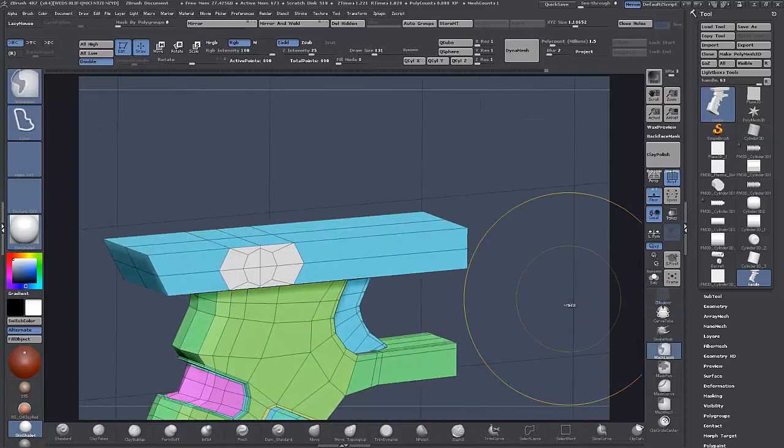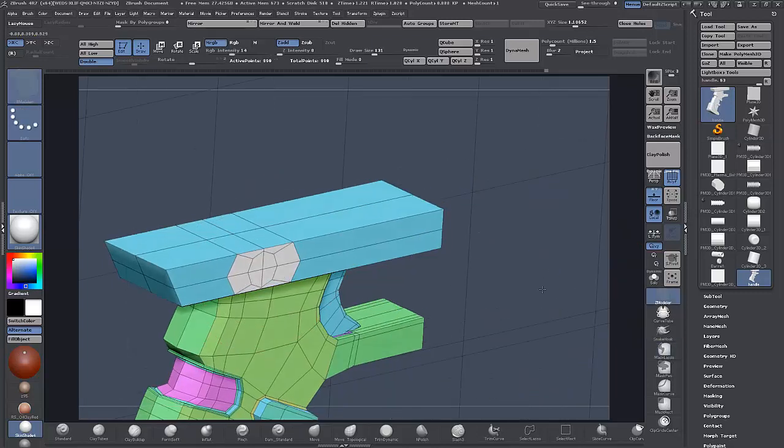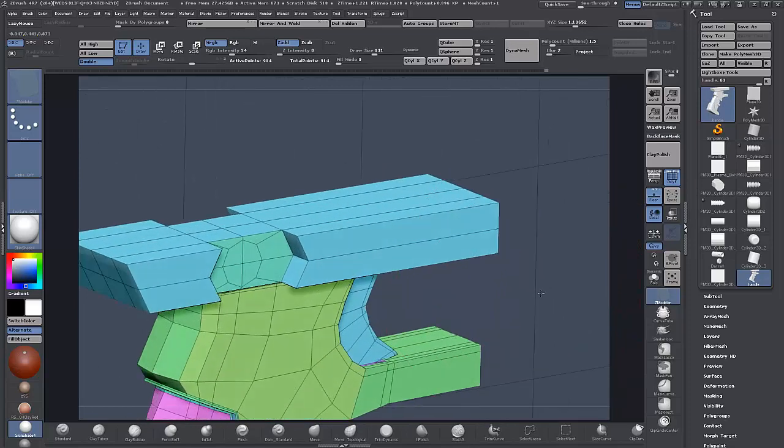Now the only problem here is, I might just insert the loop. Got a circle out there, and then we can tag these. Maybe just, yeah, we'll just Q mesh it out once, tag them again twice, and 3 times. You can also hold Alt while you're Q meshing to change the poly group.